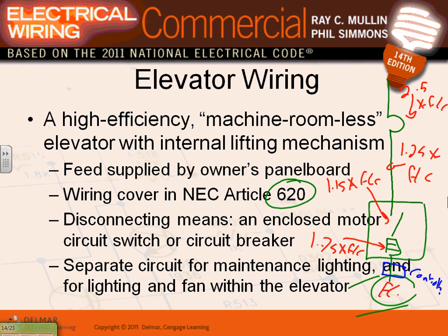Elevators have their own controller, guys. Don't even mess around with them. So this is really what you need to be aware of when you have an elevator: provide a disconnect within sight of the elevator, a fuse disconnect. They always ask for a fuse disconnect within sight of the elevator.